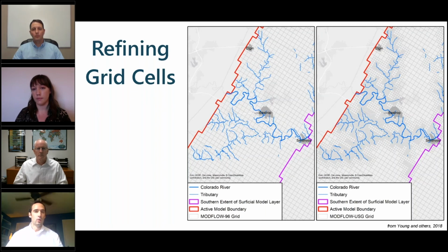So horizontally large cells might disrupt the continuity of your geologic deposits that you're trying to simulate. You can get isolated cells and maybe breaks in channels with high conductivity. So again, there's a fine line between going too coarse or too fine here. Just to note on methods, you can use local grid refinement in an area where you really need to zoom in, or you have a lot of fine-grained detailed data, or even an inset model, which is typically not done for GAMs, but that's an avenue, or you could use variable grid spacing.